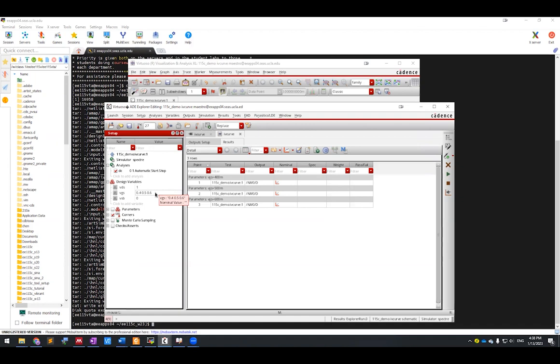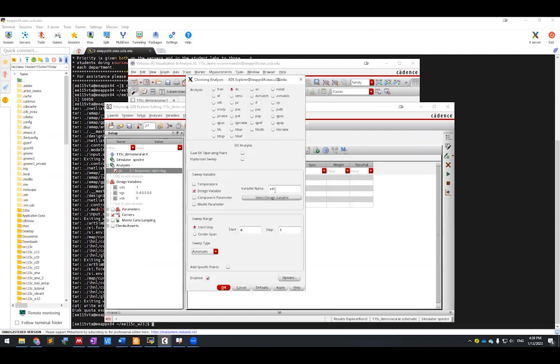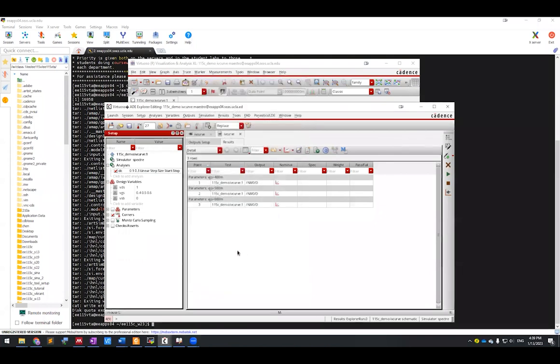So this is for different VGS, sweeping the VDS. We can do another thing that we showed in the discussion, that is to sweep the VGS and see what will happen. So now we change the variable to be VGS, linear, 0.1, and here we only have one VDS, so just give a certain number.